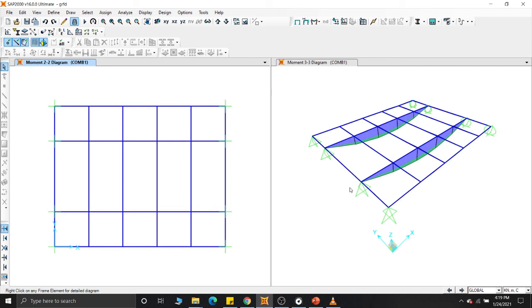have a video on how to apply moving loads, HHB loading, knife edge loading, and how to consider all these load combinations. So this is a simple demonstration of how to model a box girder bridge, just for you to have an idea, because what we essentially do is we try to get the actions, and then we try to choose our section, the section sizes and all that.